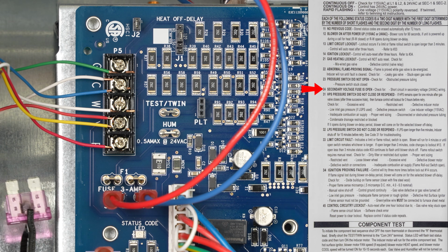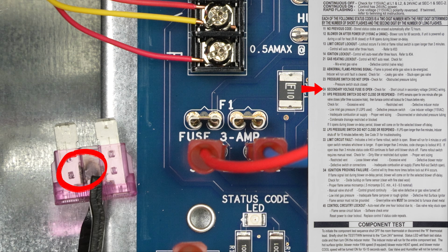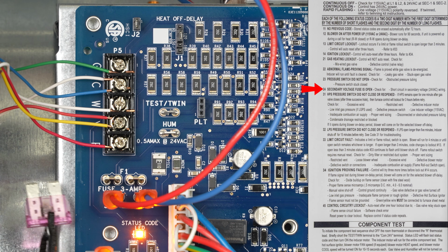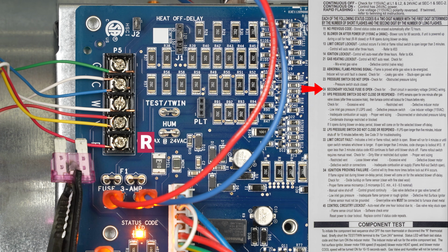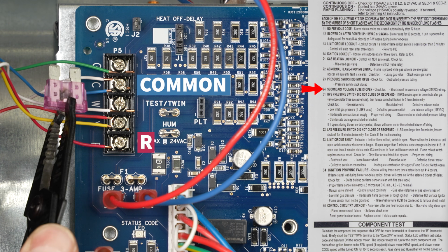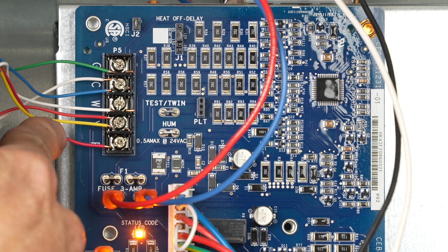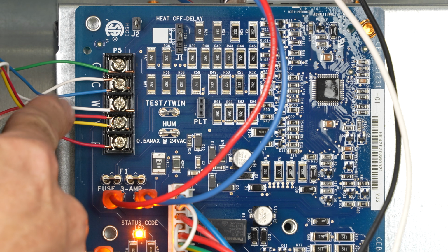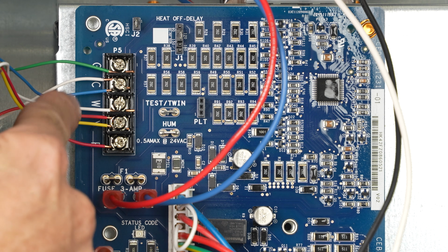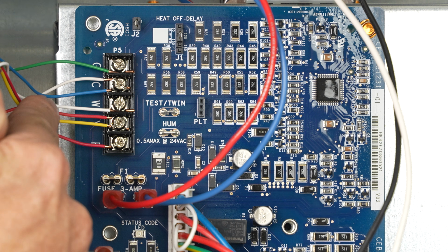And so if you can see that right there, it's a burn mark right in the middle of it. And what that means is that the R wire, the thermostat wire, is shorted up against either the common or part of the ground frame. And it may be shorted against the ground frame maybe after going through one of the other wires, say if you're calling for the fan to turn on or heat or air conditioning.